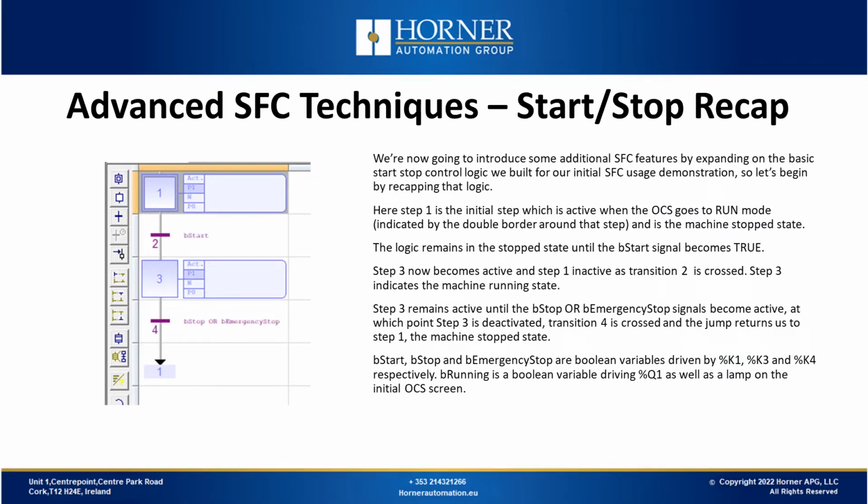First, let's do a quick recap of the SFC logic we created in our previous webinar on IEC. We first looked at SFC in IEC Support Part 1, which you can view from the webinars section on the Horner website. In that initial demonstration, we created some stop-start control logic. SFC is made up of a few main components: steps with associated actions, transitions which have associated logic conditions, and finally directed links between the steps and transitions. Steps in an SFC diagram can be either active or inactive, with actions only being executed for active steps.